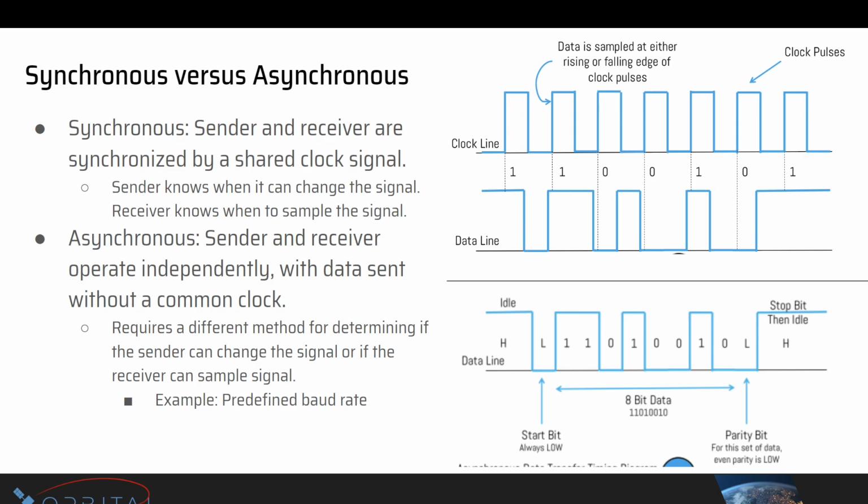Usually you would define your baud rate as bits per second, and then your device would interpret that. You just divide one by that to figure out the frequency of the data changes. For example, in the diagram, your bus idles at a certain level, in this case high, and the first bit that goes low denotes that I'm going to start sending some data to the receiver.